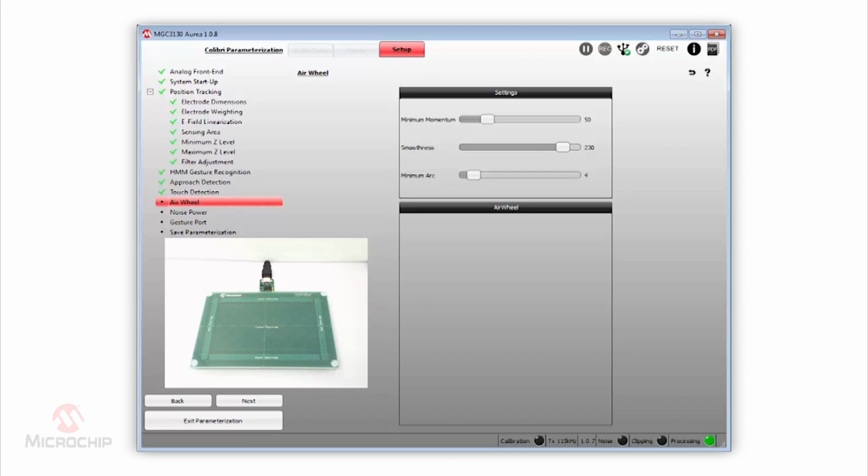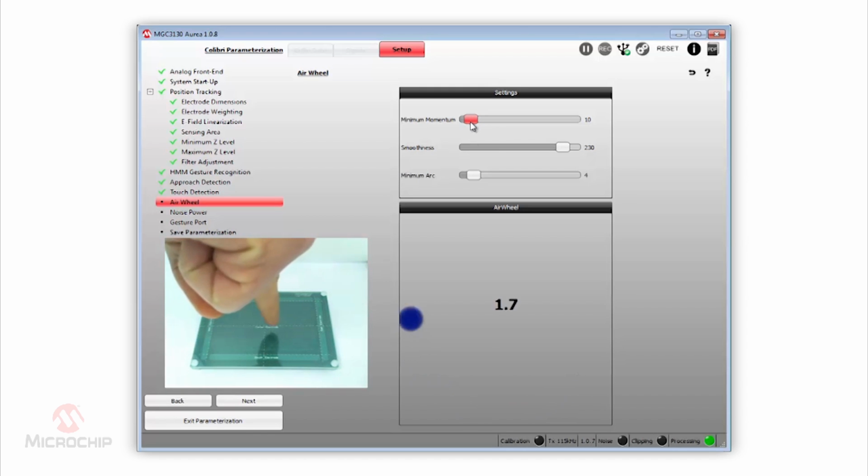Let's decrease the slider to 10, for example. If we start performing an Airwheel by doing 1 full circle and then start constantly moving our finger back and forwards without doing circular movements, we can see that the Airwheel is sensitive to these small changes. The Airwheel keeps responding to the hand movement. This finger movement can have the same effect we get from noise.